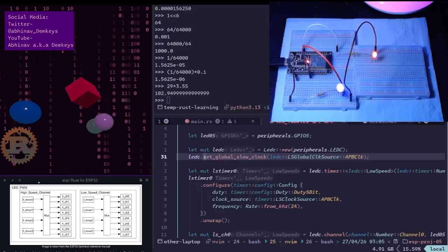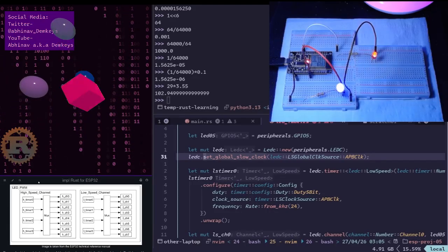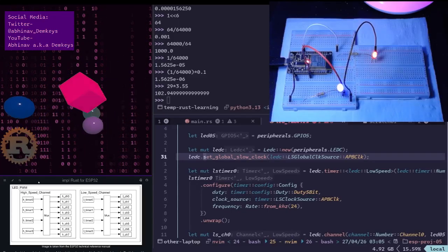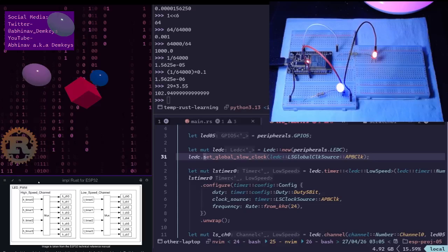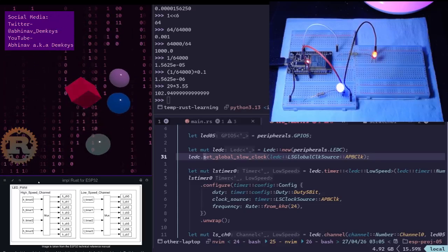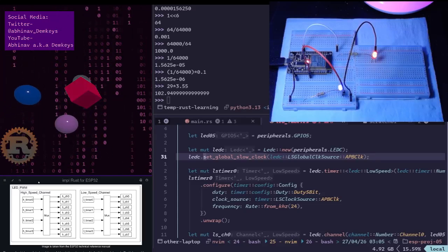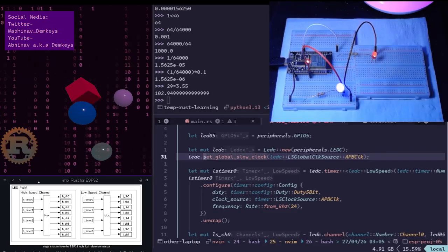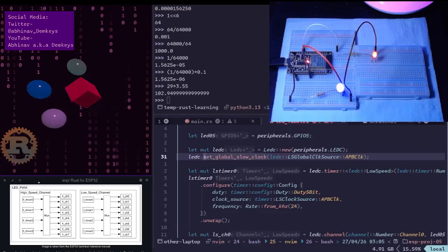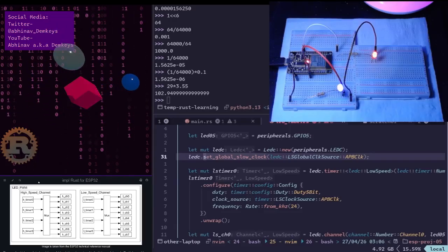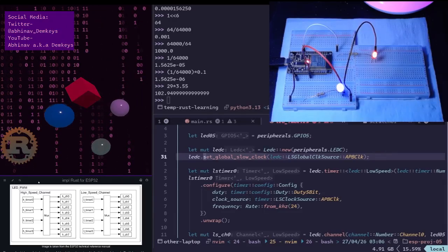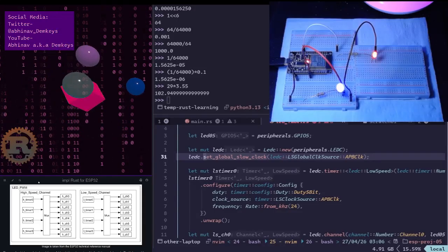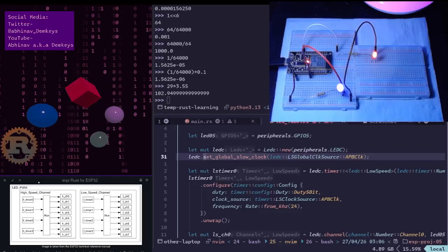Okay, so internally, the high speed channel is hooked directly into the 80 megahertz bus, so no configuration is needed. But the low speed channel, because there you do have options, that's why we need to explicitly set a value. So it says in low speed channels, it passes through a multiplexer where you must choose between the high performance APB clock or the low power internal oscillators.